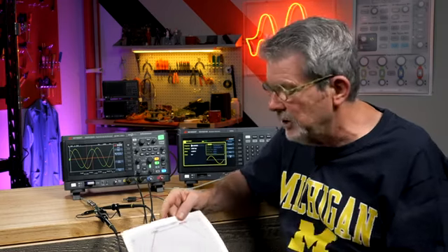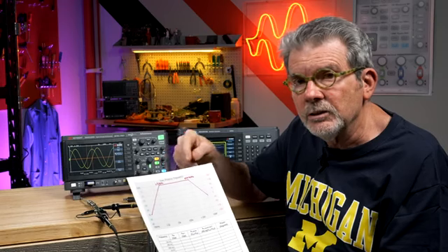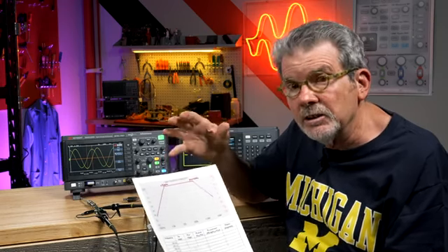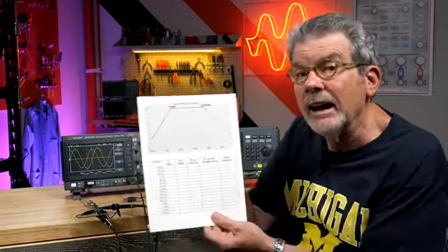So I've done a little pre-homework with this bandpass filter, the series L, C, and R, and I've determined where the poles and zeros are. There are two poles, one at 3 kilohertz, one at about 800 kilohertz, and there's a zero at 0 hertz. Now 0 hertz is off the graph.